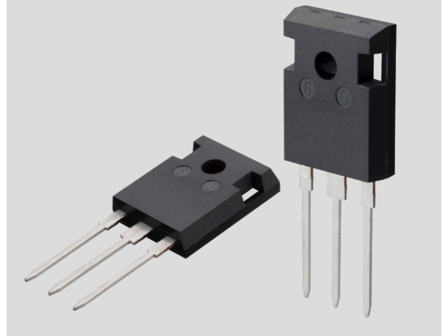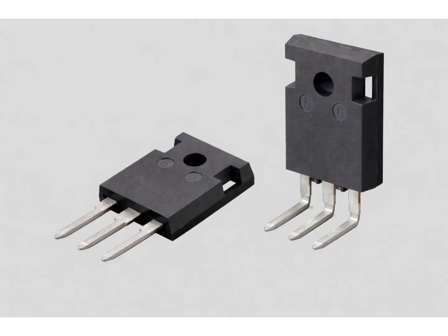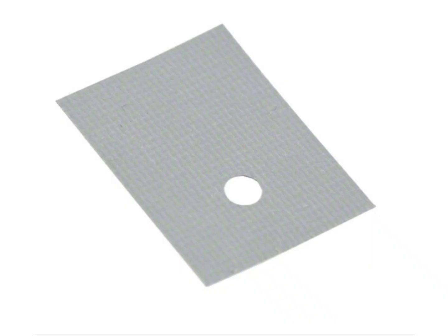Before soldering, the IGBT legs are bent by 90 degrees. This allows the PCB to sit flat against the heat sink, with the IGBT package directly mounted on the heat sink surface. Once the PCB is positioned, all the IGBTs can be bolted to the same heat sink, using a thermal pad for electrical isolation and good heat transfer.